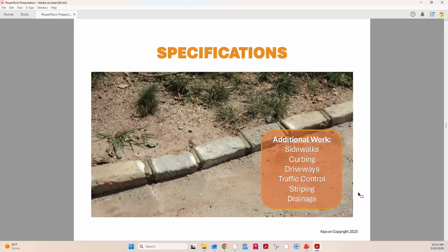If you want to do that, that's something you really want to plan for before the specs are done, so that you don't get halfway through a project and decide to restripe and find out that you can't be moving parking spaces around. So again, that's something you want to think about before you do the pavement project, and let your engineer know. It might be a case where you also may need to, as a courtesy, approach the township engineer and ask if there is anything that is required for the parking arrangements to be moved around.